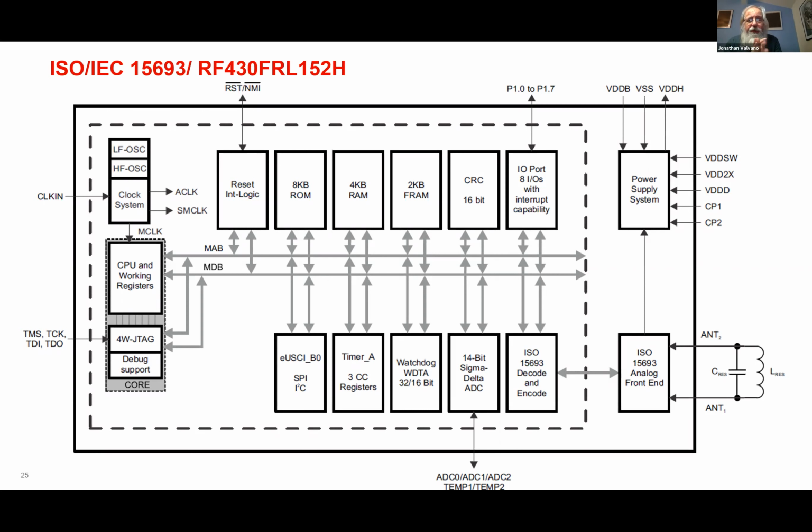There is an A to D converter on this chip, but it's going to be noisy when I'm running batteryless because it only works with the coil active. So it's basically a coil, that's the L, and a tuning capacitor, that's the C, and the rest of it is all integrated.